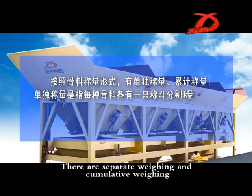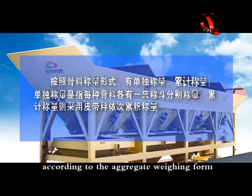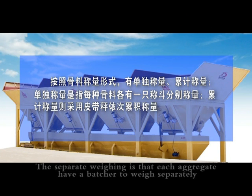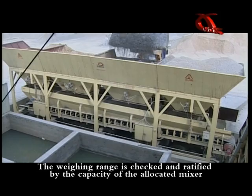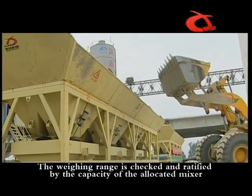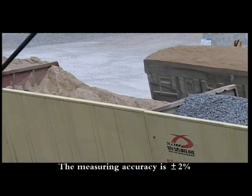Weighing may be done in accumulated or separate modes, according to the operational form. The separate weighing occurs when each aggregate has a batcher to weigh separately. The accumulative weighing uses a belt scale to weigh in shifts. The weighing range is checked and adjusted according to the capacity of the allocated mixer, with measuring accuracy allowing for a plus or minus 2% error.